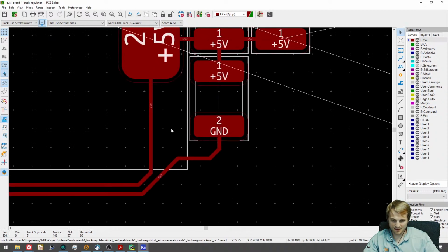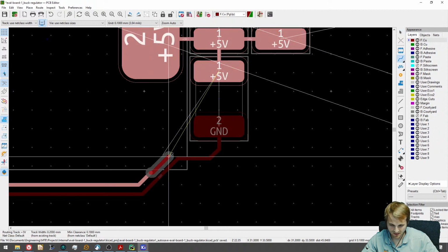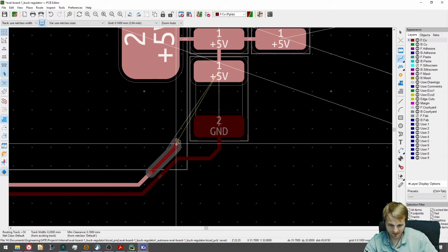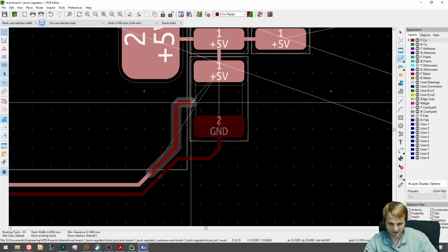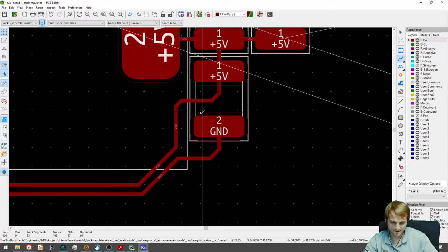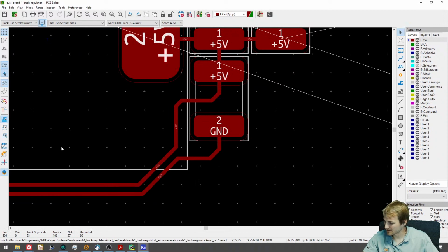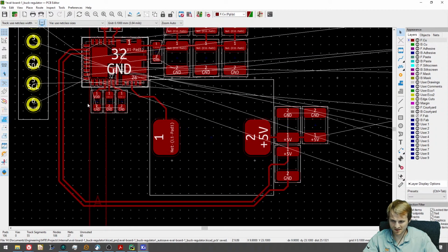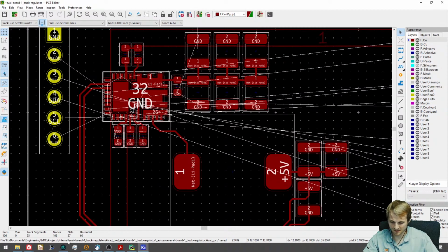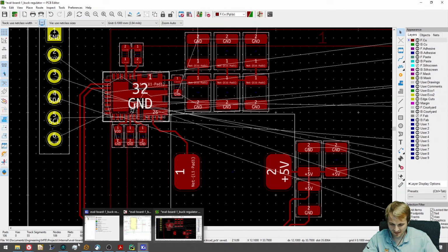So since they want these to be true differential pairs essentially, we'll do a copper keep out to keep this from just blending in with the rest of the copper. But they don't really, so it probably uses a circuit from that app note that does it. That app note shows the series resistors. If that's the case, yeah, we'll certainly come back to that.